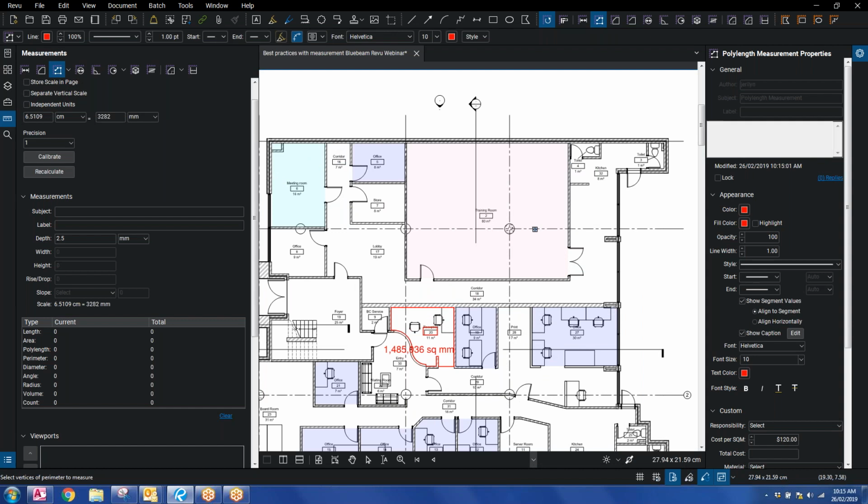So all I have to do is you could adjust properties later or now, that's up to you. So I'll just do it later, but you can see now I'm just going to run my duct run through the room like this. Okay, and straight away you can see that the values are given to you in sections as well as the total up here.